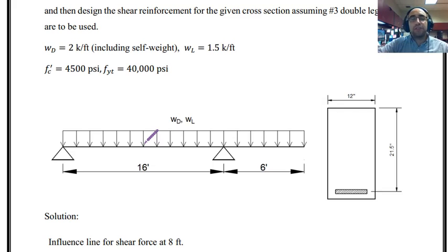Or like for the case of the simply supported beam that we solved as the previous example in the presentation file, the middle of the beam was the region where we got zero shear force, but based on the shear envelope, we could see that shear is not zero over there. If we have live load in just the left or right span, the shear might be different in that specific region. So the critical regions are the regions where we might get zero shear force.